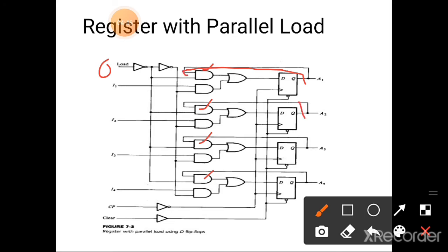Here the output is connected with the AND input, and so this present value will be transferred to the register. That is a no change condition, maintaining the content of the register. So the feedback connection in each flip-flop is necessary when D type is used, because a D flip-flop does not have a no change input condition.